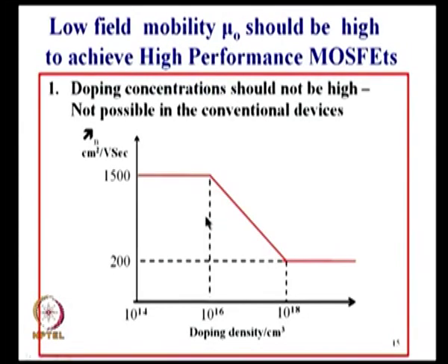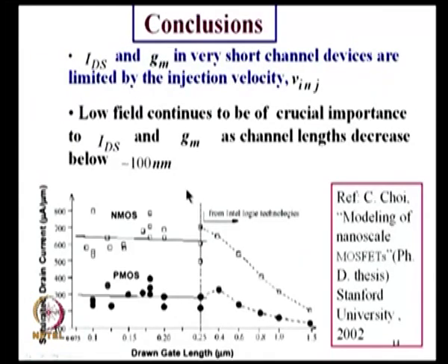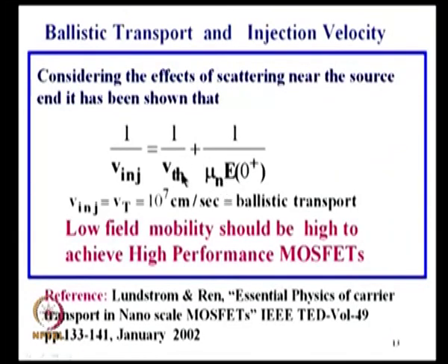Okay. So, what is our aim from this discussion? What we see is you need to have very high mobility for electrons, because after all thermal velocity is fixed by temperature, 10^7. You need to get higher and higher mobility. What is the way you can get higher mobility? What are the factors which affect the mobility? That we will see now.